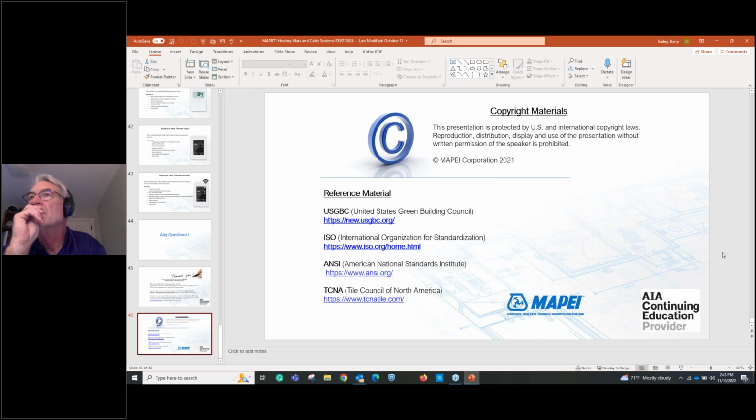You've nicked it, but most of the time, if you're ohming it, or checking the resistance during that whole time of the install and afterwards, you should be able to detect that nick. If it's just a small nick, that's not going to have a problem. But a big nick, and I don't know what they're nicking it with, but these cables are fairly tough. You would have to really, I don't know, maybe drop your trowel from up high and hit it.